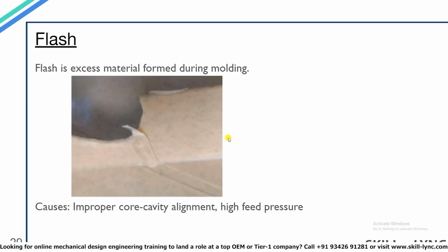Now this can happen when the core and cavity plate do not close properly, or the injection pressure is too high and the material seeps outside the mold. To fix this issue, we have to do some post-processing operations which will increase the production time.